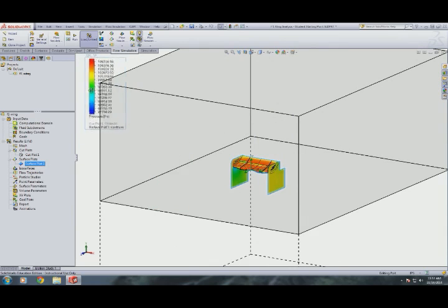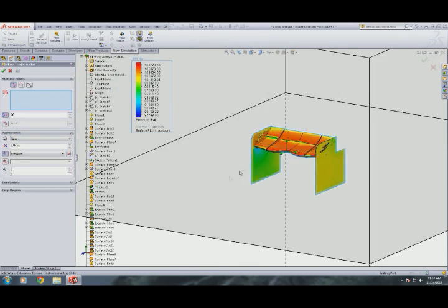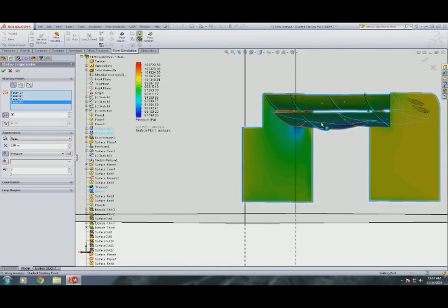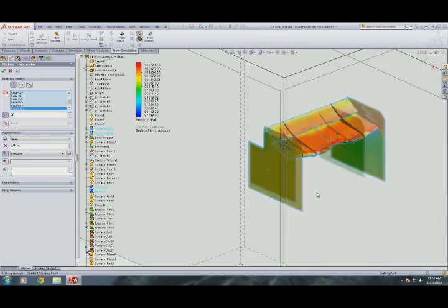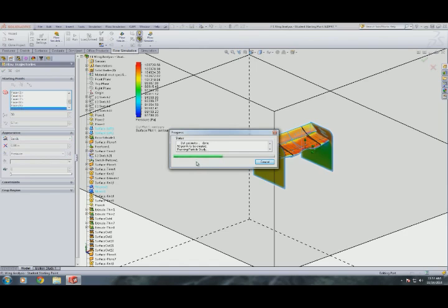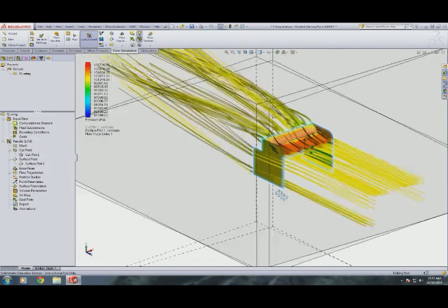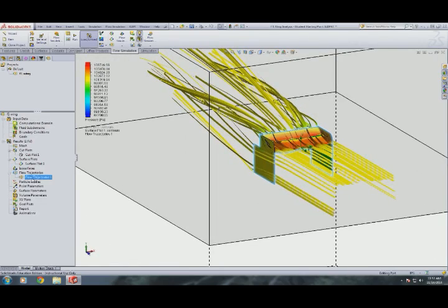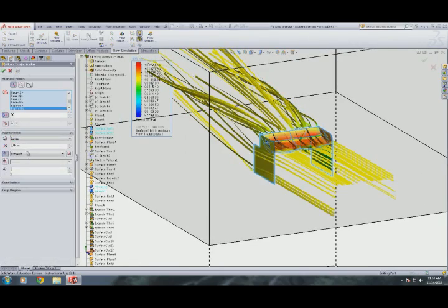We can turn on flow trajectories, inserting one. Let's have them emanate from, well, those surfaces for sure. These big wing surfaces as well. Outside panels, and yeah, it should be fine. Let's do like 50 of them. Pipes are okay, but I think bands are more interesting. Marching bands are really the best, but these will do. There we go. So bands, I think we have them pressure colored by default. Yeah, so the color evolves as pressure changes on these things.